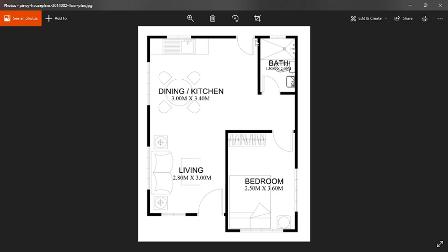Okay, so this side appears longer than from here to here, so it's probably from here to here is the 3 meters, and the longer side is the 3.4. Then from here to here we take the smallest size, which is 1.3. So this is what we're going to do. We're going to draw a wall 3.4 meters, then plus 1.3 meters from this point to this point.